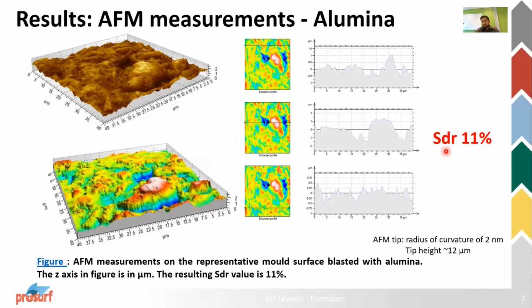So this parameter is basically the ratio of the effective area contributed by the texture to the area of a leveled surface. If it's a completely leveled surface, the SDR would be 0. But if it's a textured surface, the higher the slopes, it will keep on increasing. It takes into account both the vertical height and also the lateral spacing of the features in a measurement acquisition area.